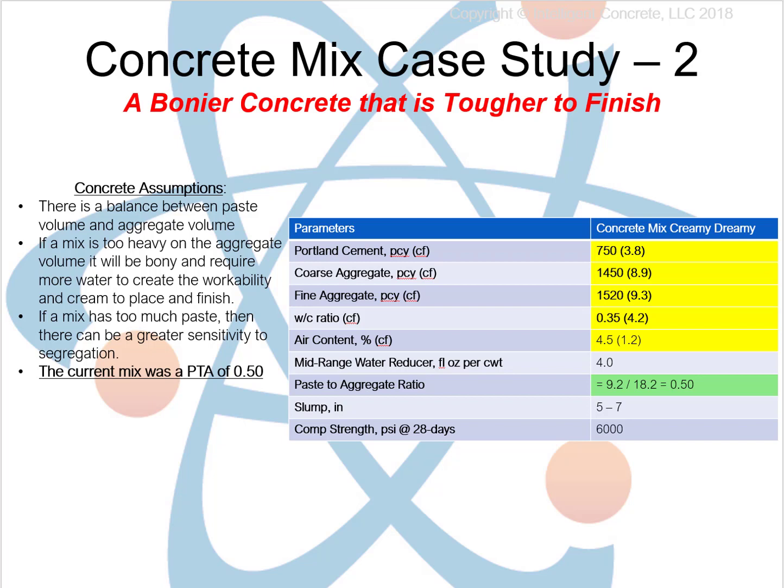And to reclaim or to reinvigorate, to bring the mix back to life, to that creamy and dreamy state, more than likely we've got to add water to it. Now, if you remember back to the last mix, the bony mix, we had almost double the amount of high-range or mid-range water reducer, and that makes a lot of sense. We're not getting that fluidity, that workability, that finishability from the water or from the paste,